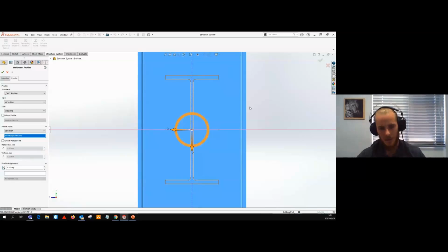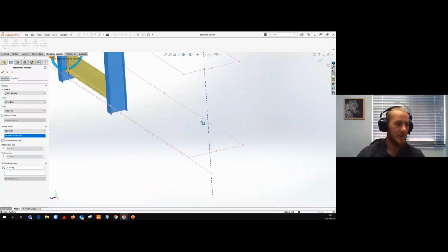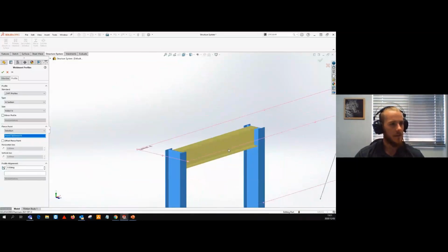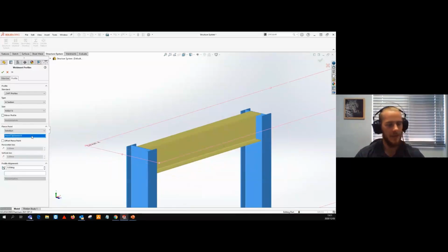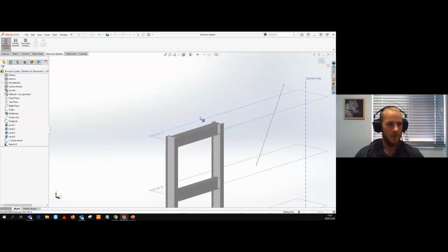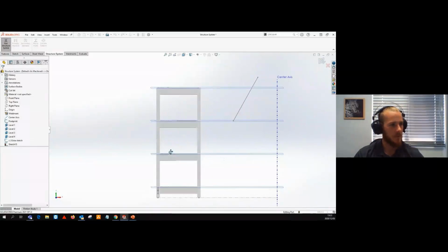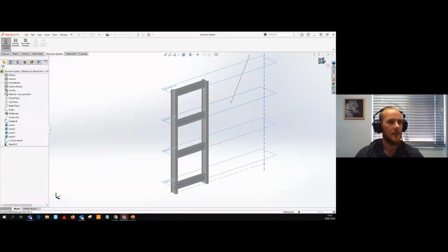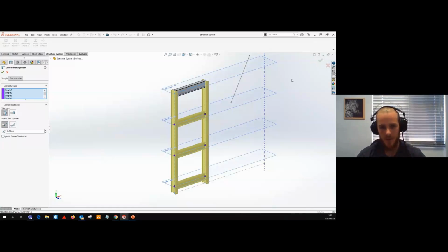So for this structure to be complete, we need the top of this beam to rest flush or on top of the plane. So all I do is select an additional or new point, and you guys can all see what's the effect. I've basically gone and just lined up everything quite nicely by assigning a different pierce point to the reference. So from here, guys, I'll just say okay, and you guys can see my member structure coming together quite nicely. Last but not least, I'll hit the exit button, and this is where the corner management automatically kicks in.